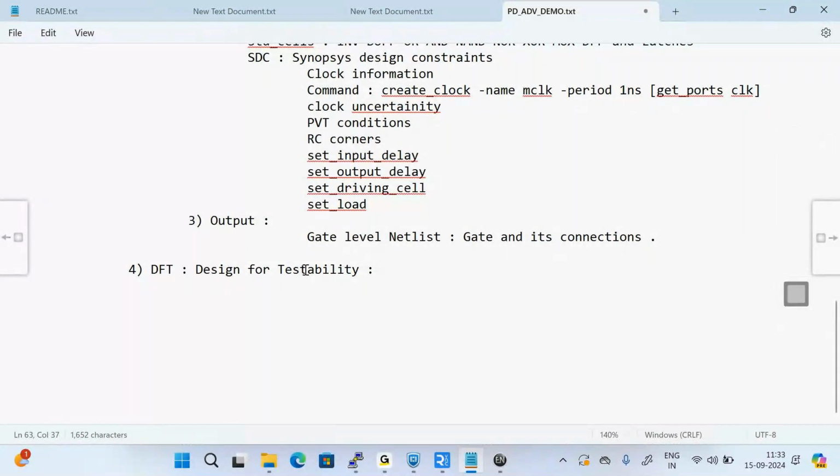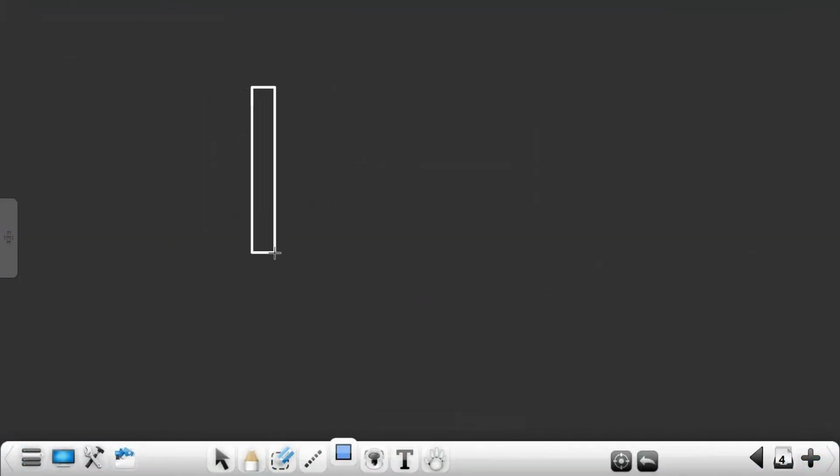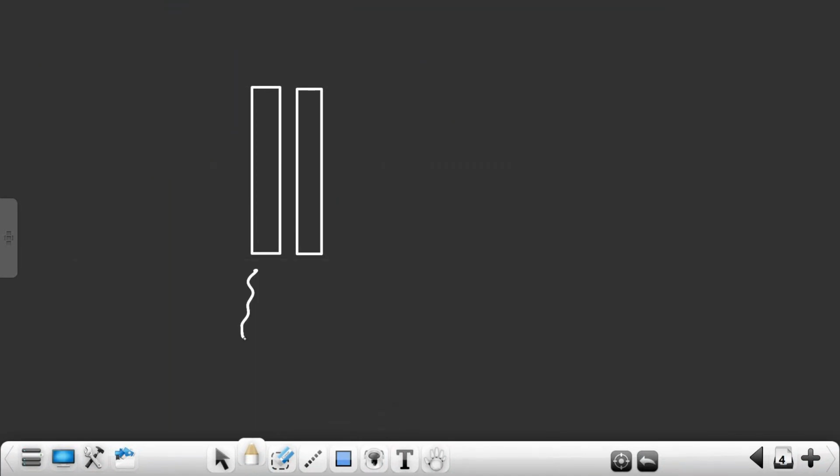See, when the chip is tested, they cannot use this chip directly in laptops, or directly in phones, because during foundry fabrication also they will make mistakes. Fabrication mistakes happen. Sometimes metal layers are not fabricated properly. This is the actual metal layer I want to be fabricated, but during fabrication the metal layers are fabricated like this. So without knowing, both are what? Shorted.